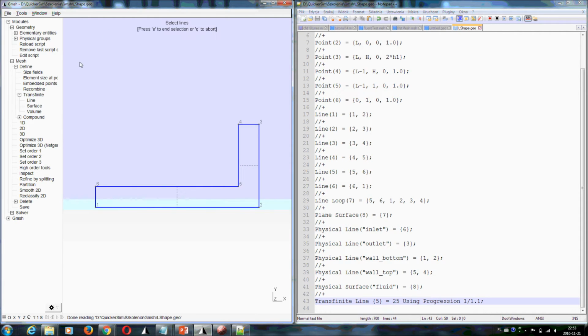Let's open recent 1D, 2D, and you see a very nice refinement to this edge. Right now I'm going to talk about size fields. In many situations, if you want to solve structural dynamics, you might have big problems at sharp corners, because cracks and things like that can be generated under tension. The same happens in solving fluid flows.